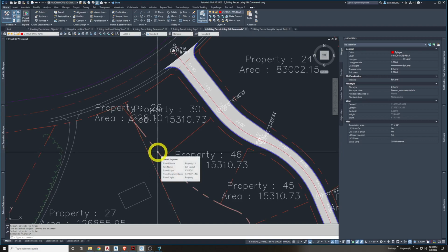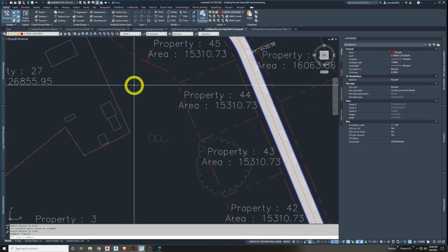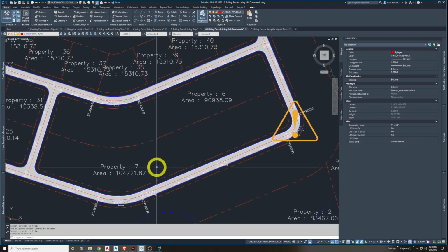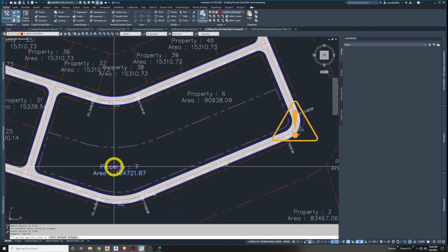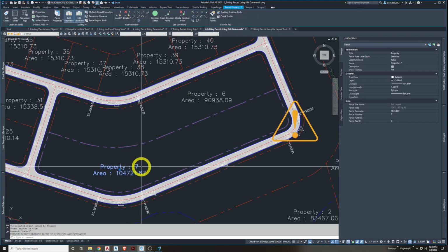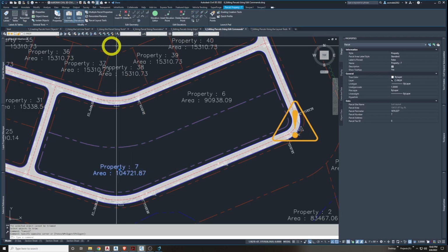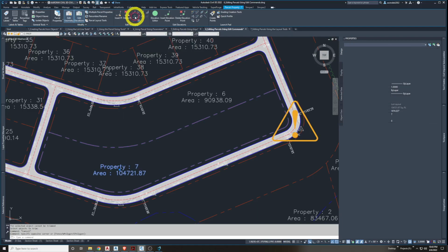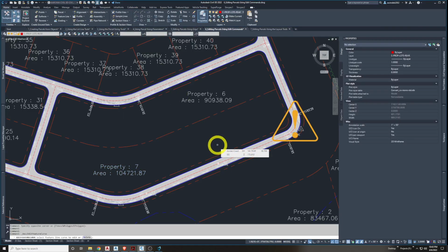We'll go to step 6, property 7. We'll click on property 7 to get the parcel queued up, and then we're going to go to the edit curve option here. It edits the radius of a feature line arc, parcel line arc, or survey line arc. So feature lines, parcel lines, and survey lines. And the new arc is displayed as we go. So let me pick that.